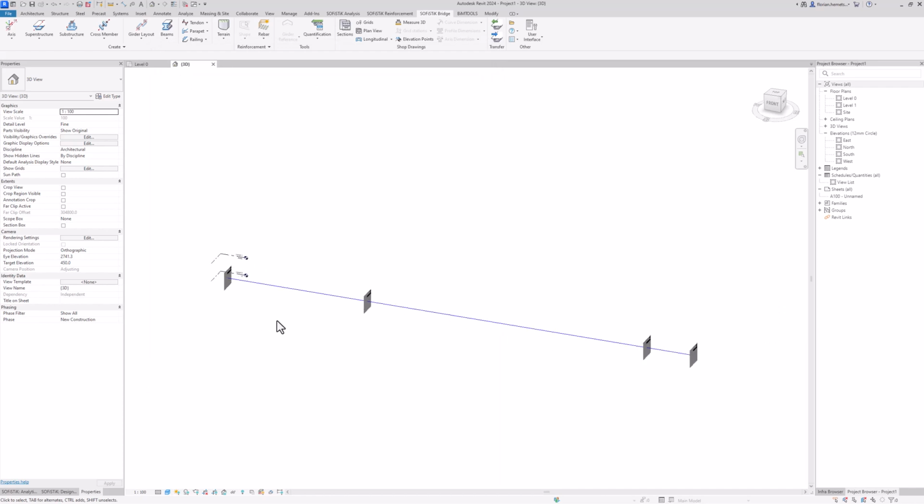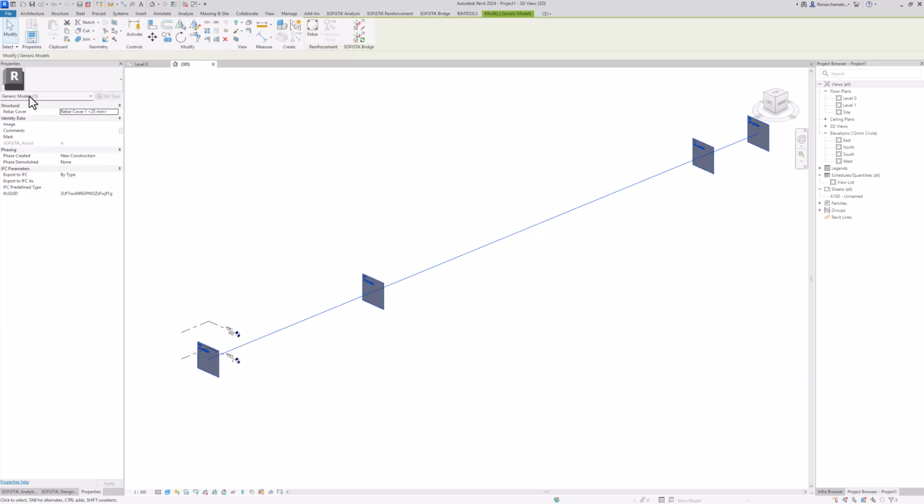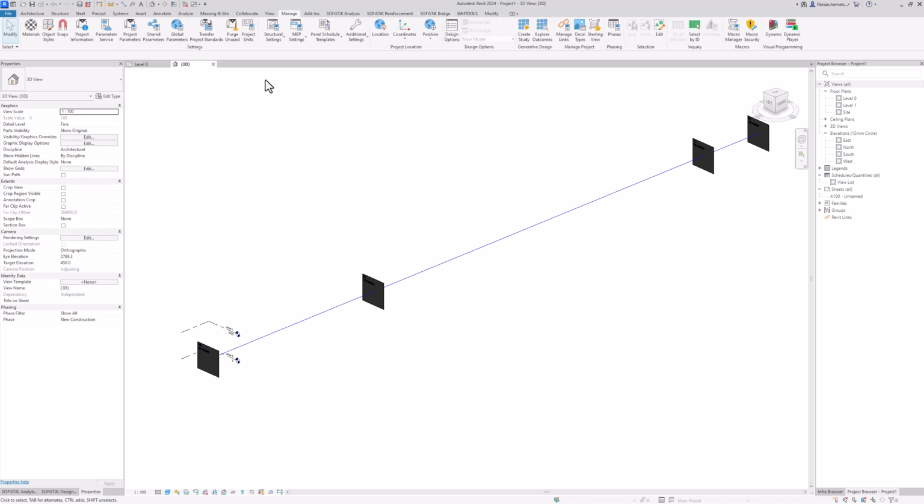We can immediately see that the axis is created in the three-dimensional system of my project. But all we do here is create complex Revit information, like you can see here that this axis is actually a native Revit family, generic model, which means that we can modify all these inputs by managing our inputs from Revit. For example, I don't want to have my length input in millimeters, I want it in meters and also display the unit.